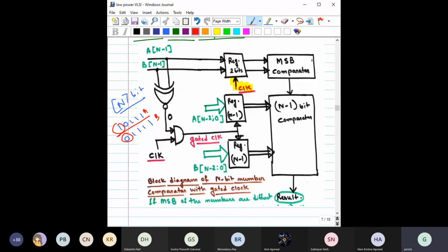So when you are not comparing the remaining bits, how do you compare? You have to do some operation. Which gate will help you in comparison? XOR. So the XOR output has to change, right? Is it really required to check this many bits, if you can check only the first bit and tell that this number A is higher, right?